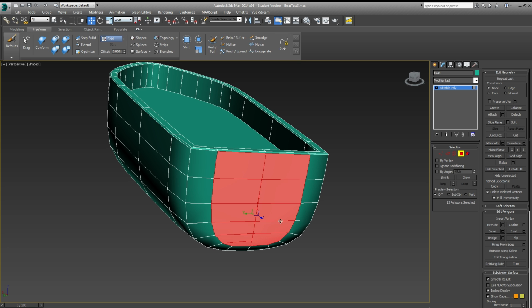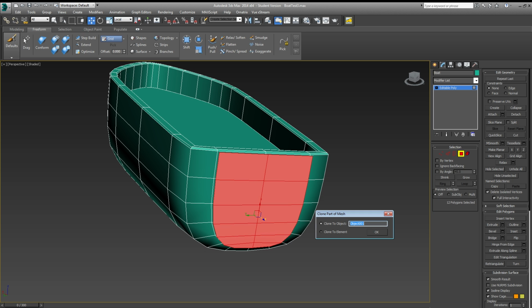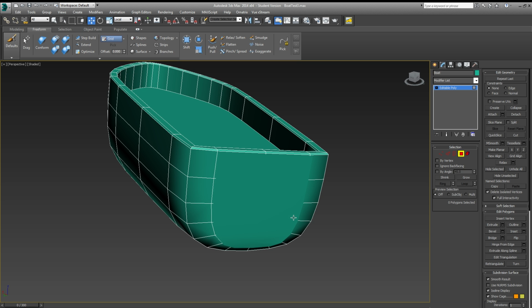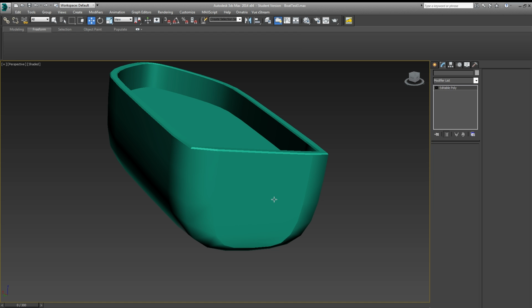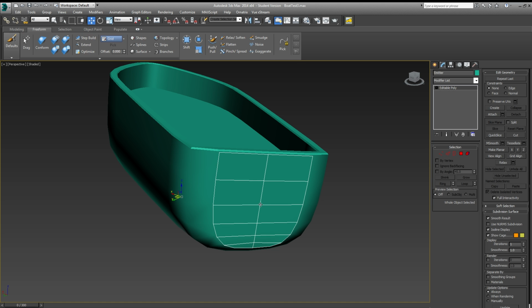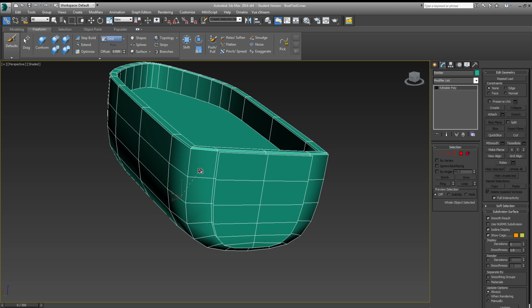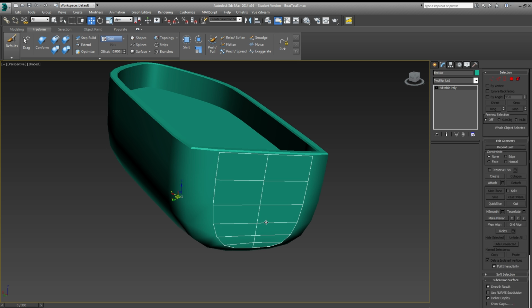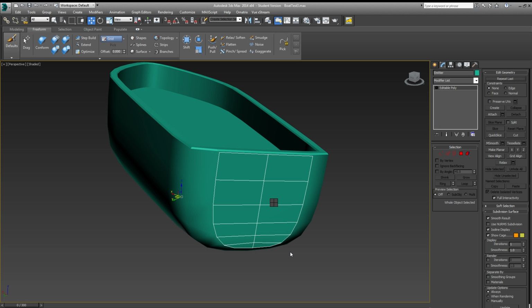and I will go into my local coordinates up here, and then I'm going to hold down shift and drag these out a little bit, and I will give these a new object name, and we'll call these emitter. So basically what I want is for this to be linked to our particle system, and these will emit the particles.